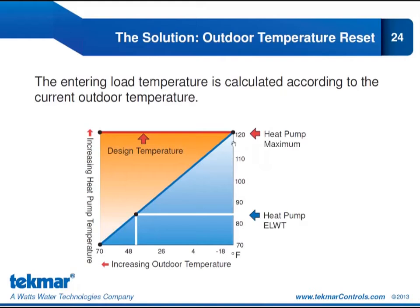So the blue line here is what we call our outdoor reset curve. And you can see this outdoor reset curve varies according to outdoor temperature. So when we have extremely low outdoor temperatures, that's when we're going to see our design temperature at 120. However, as the outdoor temperature increases, we don't need that 120 water.